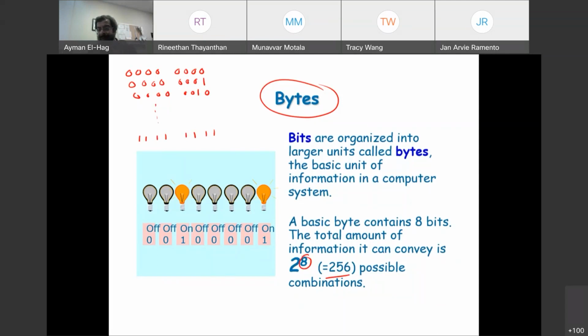So your signal cannot be continuous, cannot take any value. It has to take values from the start to the end, among these 256 different levels. Only. You have only 256 levels. Your signal can be one of those 256. It cannot be in between. So this is what I mean by resolution. How good is your card, how many bits does it have, so what is your resolution level? What is the minimum signal you can measure, as we will explain more.